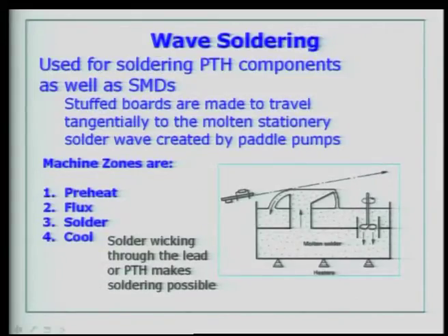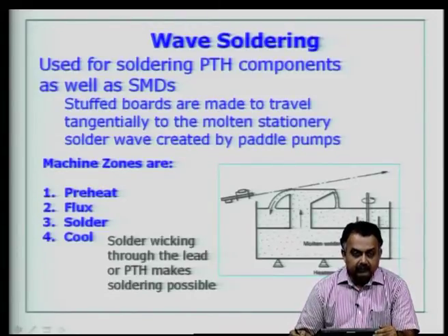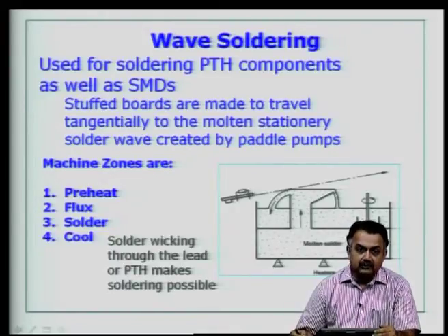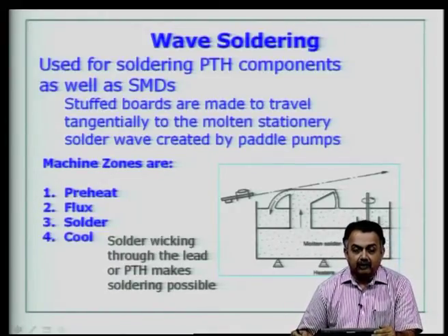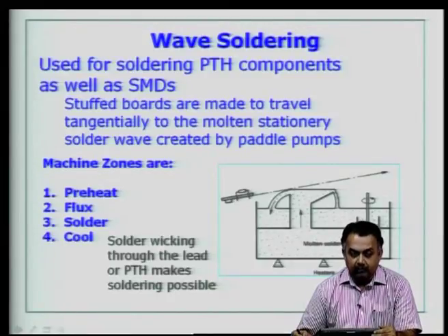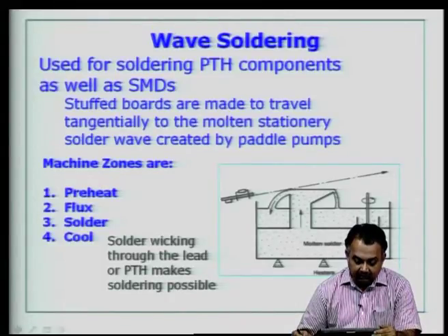Wave soldering is another process that is used for soldering through hole components. But initially, when surface mount technology was beginning to take over, wave soldering was used for surface mount devices. Today, most of the surface mount devices have qualified themselves for reflow soldering process because it is much more accurate, gives more yield, and probably you can control the temperatures using a reflow soldering process, avoiding thermal shock to the